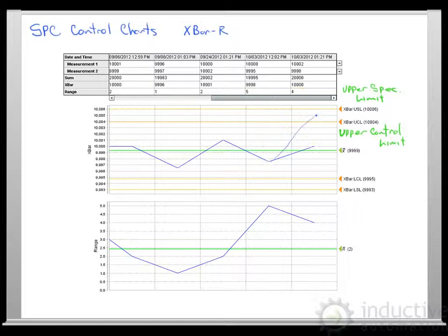We can also have control limits down on our range chart as well, saying that, yeah, we're starting to be more inconsistent and we need to take a look at what's going on and why we're suddenly getting a little sporadic on our consistency. Also, you really don't achieve a range of 0 in most processes. It's healthy to have some variation. That's very natural. If you do have a range of 0, that's kind of an indication that maybe the sample data is not correctly being taken.